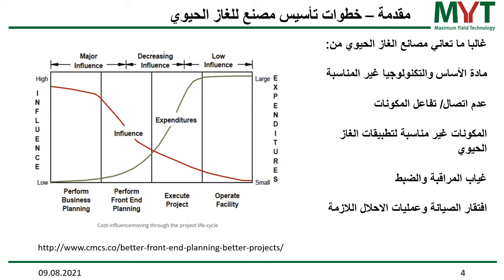Lack of monitoring and control is often an issue if you have specific substrates, and process control requires action, and you don't have the monitoring to actually control or to observe what's going on in the plant, and this causes a lot of issues in your biogas operation. An example here is H2S concentration in the biogas.